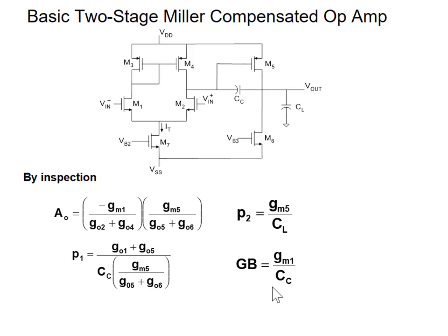Oh, we just went through this now. We talked our way through this and wrote down the gain, the pole P1, the pole P2, and the DC gain. The only thing we're missing here is that zero. What? You say we don't see them? Or you don't need to worry about them or something like that? Pardon? When you say zero is one big deal, well, they do affect the frequency response a little bit. They don't affect the stability.